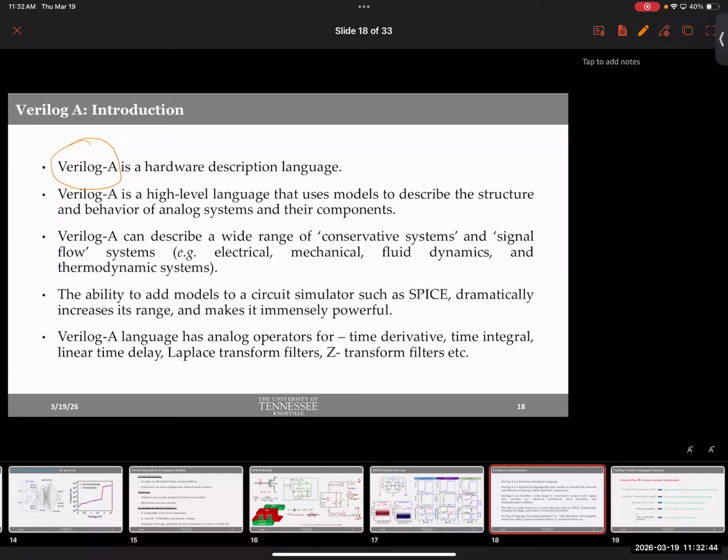Typically, A stands for analog. There is a reason why we mention that, because for the most part, it is very powerful when it comes to mimicking analog properties, right? If it is just zeros and ones, then we have other simulators and other modeling tools that we could use just for digital electronics, simpler to represent. But analog electronics, for example, a memristor is a fully analog device.